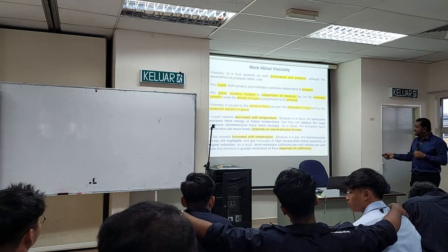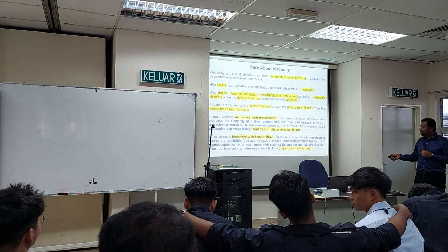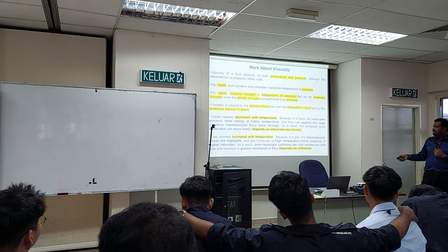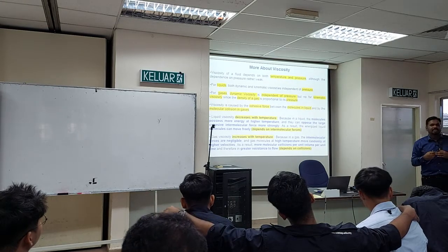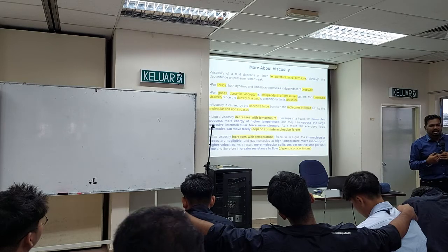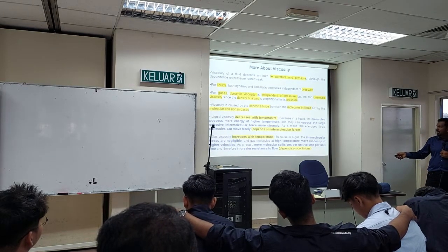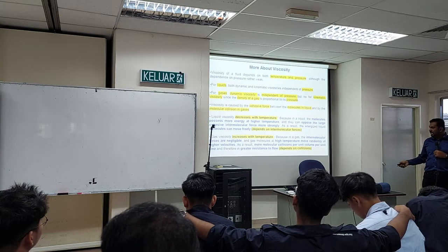As a result, the energized liquid molecules can move freely. Okay, it depends on the intermolecular force. Okay, so what it is saying, because the cohesive intermolecular force is decreasing, the molecules can move freely, so the viscosity is lesser. So that's what it tells us here. Why, when the temperature increases, the liquid viscosity will decrease. But gas is the opposite.